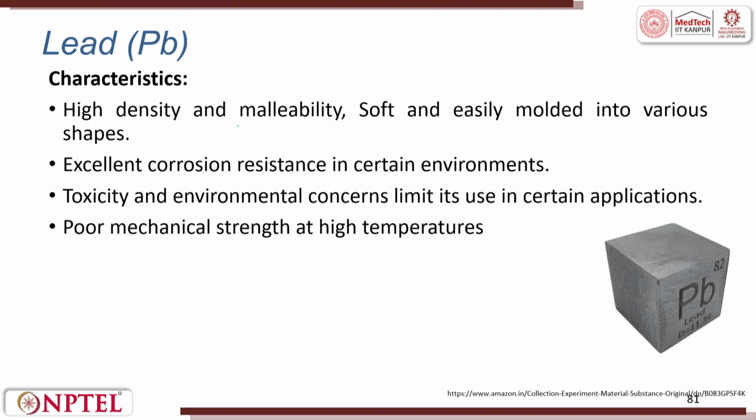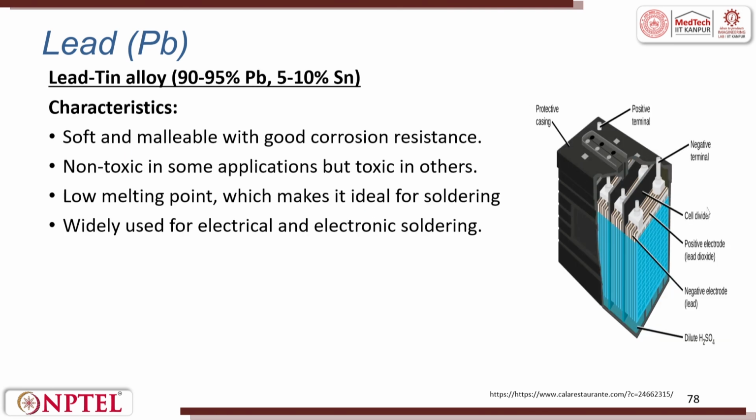Lead has high density and malleability. It is soft and easily moldable into various shapes. It has excellent corrosion resistance. Its toxicity and environmental concern limits it to certain applications. It has poor mechanical strength at high temperature. That is why it is used exhaustively for electronics applications. As you know, lead is very soft, but very heavy.